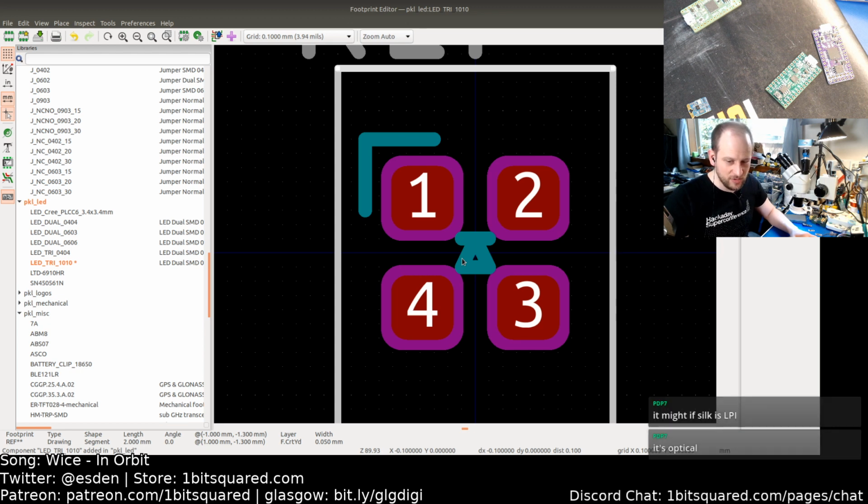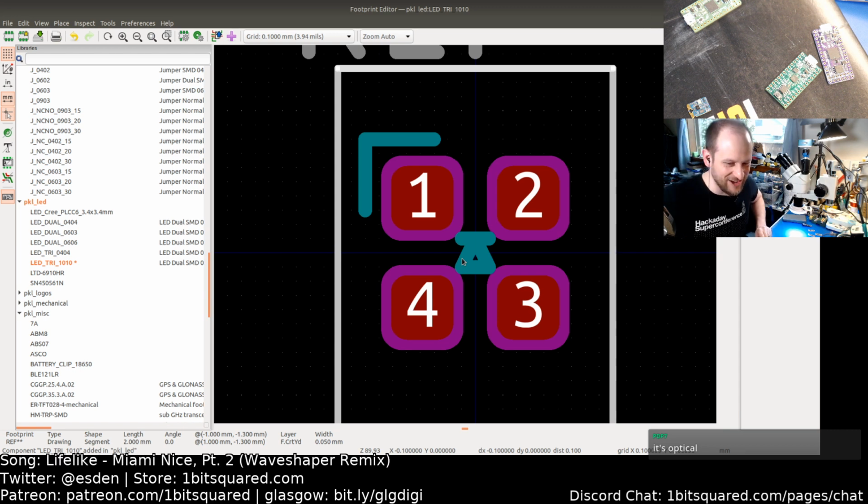Because if you just do, well, it's optical. Yeah, I know, but if it is optical, everyone else would use a solder stop process, and with the normal solder stop processes, you cannot stack two of them on top of each other without one peeling off of the other. They don't like to stick to each other, the solder stop stuff. I tried. So it is trickier what the materials are being used than one would assume at first.